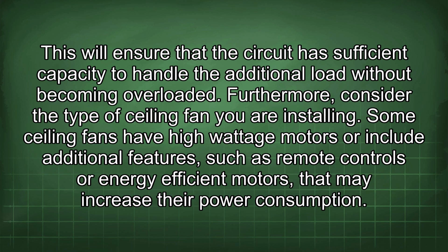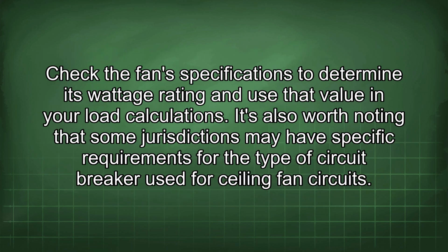Furthermore, consider the type of ceiling fan you are installing. Some ceiling fans have high wattage motors or include additional features such as remote controls or energy-efficient motors that may increase their power consumption. Check the fan's specifications to determine its wattage rating and use that value in your load calculations. It's also worth noting that some jurisdictions may have specific requirements for the type of circuit breaker used for